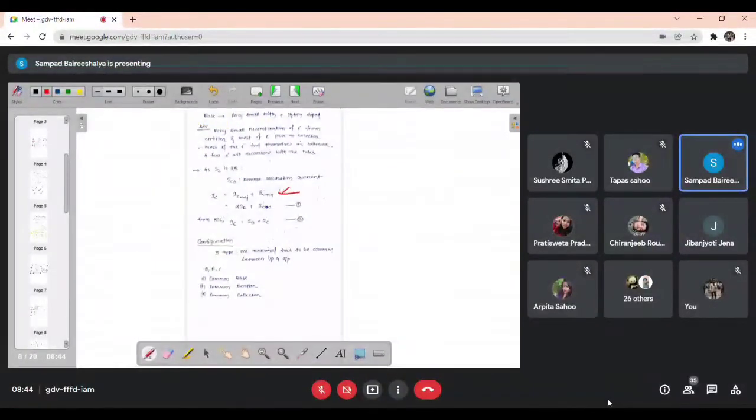Okay, and this majority I just mentioned: in this situation, N amount of carriers are generated here, so here it will be alpha N, because alpha is a bigger number, meaning more towards N. That means you can say 95 to 98% of the majority carriers will reach over here. Yes or no? Okay, that means your IC majority will be nothing but alpha times IE.